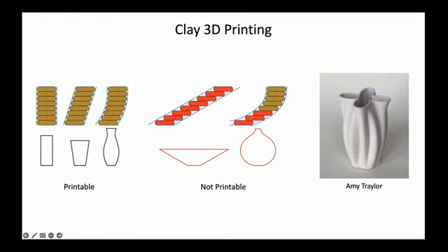When 3D printing in clay, clay must be wet and soft, and it remains that way for a long time until it dries due to evaporation. Clay is also really heavy, and therefore many forms with extreme overhang angles are prone to collapse when printed out of clay. Because of clay's properties, there are limits on what forms can be 3D printed out of clay using traditional and commercially available software.